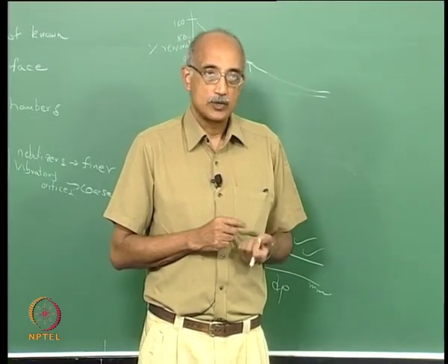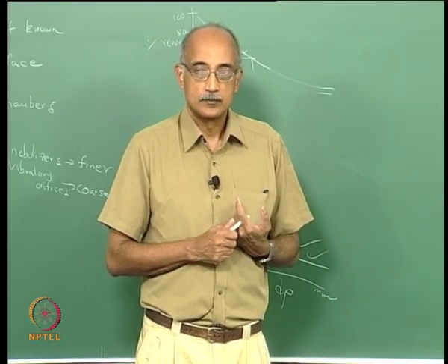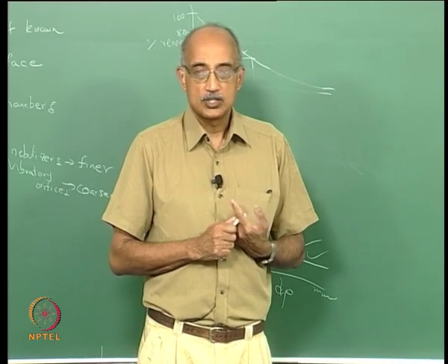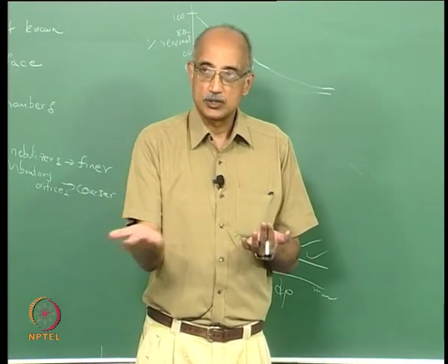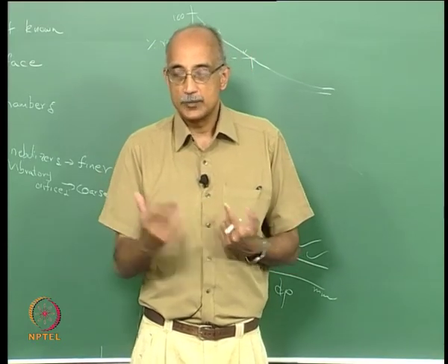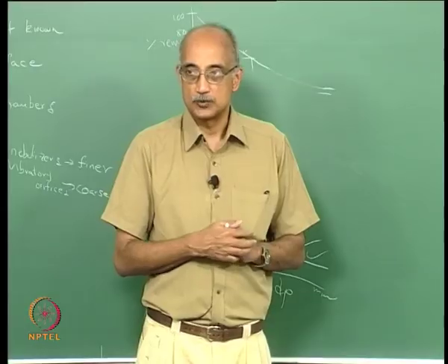Any questions on what we have talked about today? Yes. Plasma cleaning is the same, you charge the particles and pour them out? No, you actually charge a gas and you expose the surface to the gas. The plasma interacts with the impurities on the surface. It typically vaporizes it. For example, if you have a hydrocarbon on the surface, when you expose it to a plasma, it converts the hydrocarbon into CO2 and H2O. The CO2 goes off, the water is removed from the surface.